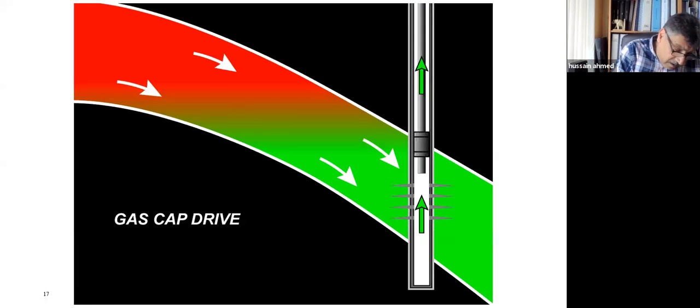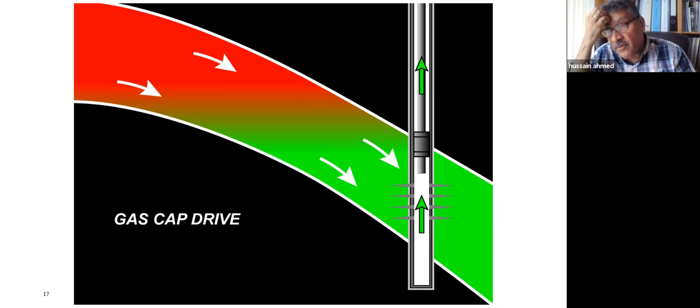Because at the end of the day, if you want to talk about optimization and how long the wellbore will stay with you, how long I can keep this wellbore alive and producing, and also keep the reservoir alive and producing, you need to understand primary recovery: how much energy I have in the beginning from the gas cap or from the water drive, or a combination of them. That will give you a future vision for your reservoir.